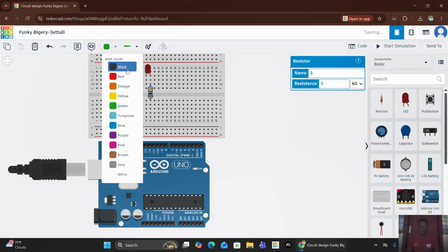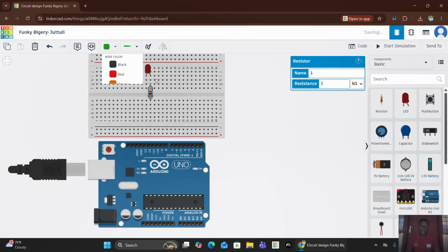So for wiring this, we will start from here, the anode. Looking at this carefully, as I explained earlier, this row, all of them are linked together, meaning connecting up here means electricity can pass down here. And on the other hand, connecting at one point here means you have supply to this whole column. So without waste of time, we'll be connecting this. This is the node that's positive. So we'll just need a wire from here.